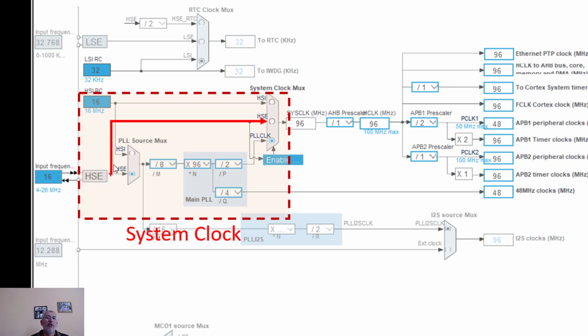So the clock information comes through here, and then we are using a phase lock loop to come up with all kinds of frequencies that we desire. It has these prescalers, which are nothing but dividers and multipliers to come up with the specific frequency. Okay, so that's another part of your microcontroller clock configuration.